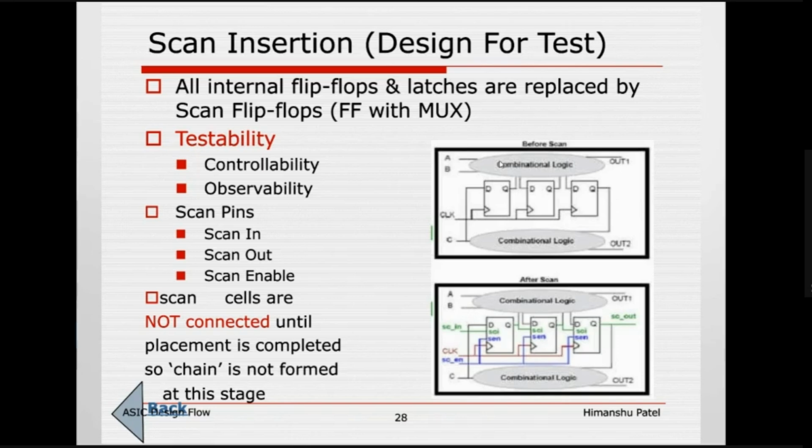Now you use this flip-flop and create a scan path. Once you convert these D flip-flops into scan flip-flops and stitch all these flip-flops into chain form, you give it to the tool and ask the tool to generate patterns, or ask the tool to test this design.